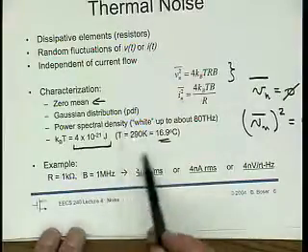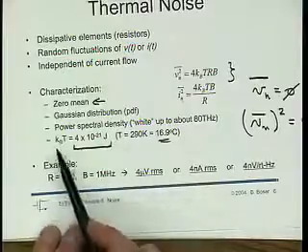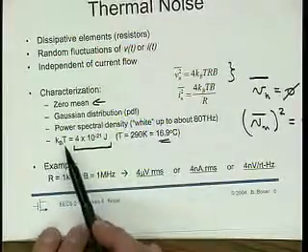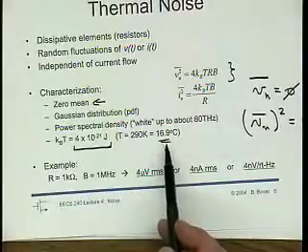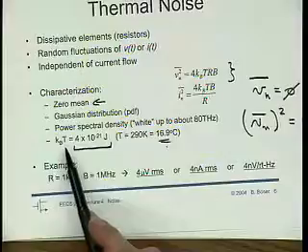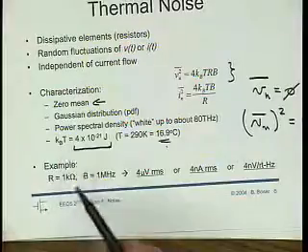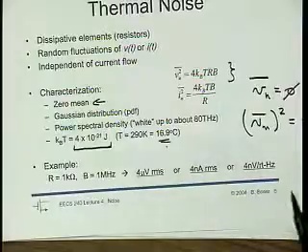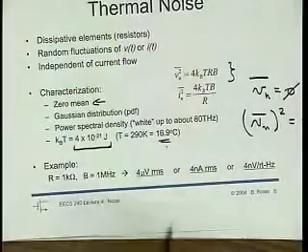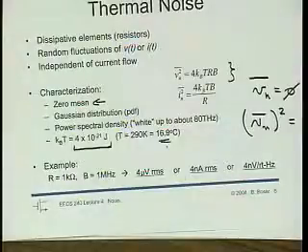When you actually analyze your circuits, you see right away that my circuit would perhaps run fine at 17 degrees Celsius. At 100 degrees Celsius, of course, I would get extra noise, and then it may not work so fine anymore. That's why in SPICE there is a way to set the temperature, and we have to run it also at the high temperature, and that's probably going to be the worst case noise.